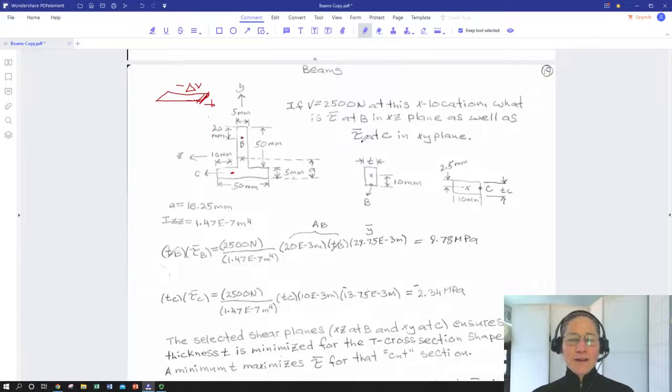So let's go ahead and look at applying our equation. Let's start with point B. We want to know what the shear is at point B. So what we're going to do is make a cut, and we're going to define a little shaded area up here, and it would go back in the x direction. So we've got another little shaded volume that we have going. I'm going to erase the back part of that because we really don't need it, and it's interrupting some of our dimensions we need for area.